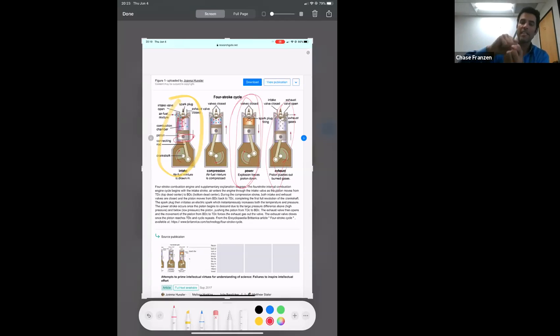So the intake is creating space in the cylinder. The power stroke is creating space in the cylinder. Connecting rod ties it all together. So as those 2 cylinders are opening, the compression cylinder is closing and the exhaust cylinder is closing. So all 4 strokes: suck, squeeze, bang, blow, intake, compression, power, and exhaust. Again, all of those connecting rods are tied to one crankshaft, and that crankshaft is turning, and that crankshaft is connected to the propeller, and ultimately that's what's turning the propeller.